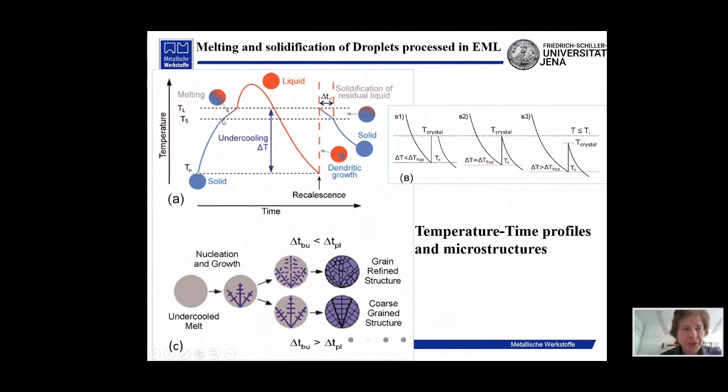from room temperature up to the first critical temperature consistent with the solidus in the case of an alloy. In the case of a metal, we have just one critical temperature, the melting temperature, but anyway, in this case the slope of heating decreases. It goes with a smaller slope due to the fact that we need to bring a lot of heat in order to melt, in order to destroy atomic bonds in the crystal lattice. Because of this, the slope will be smaller. However, we come to the complete melting at the liquidus temperature,